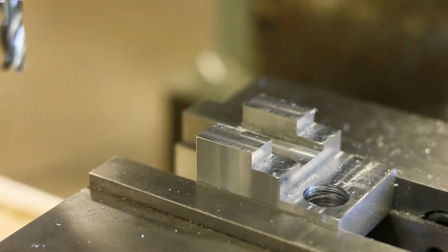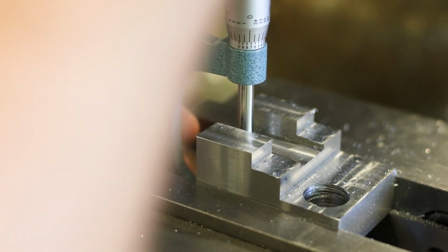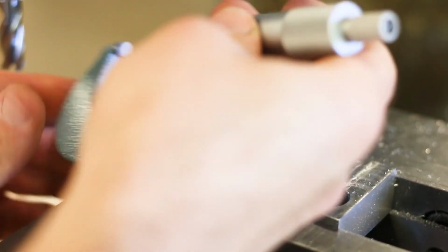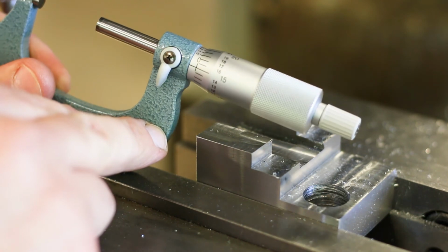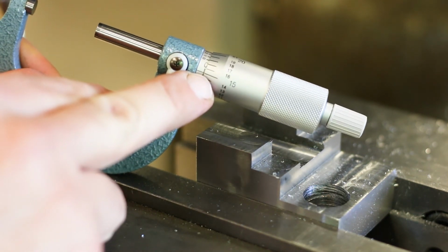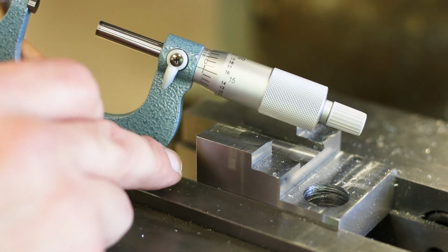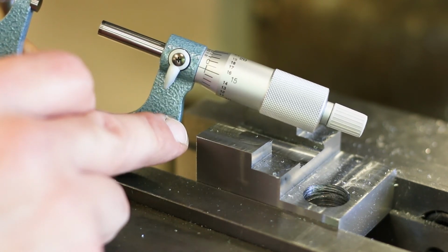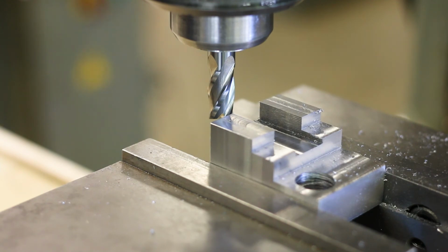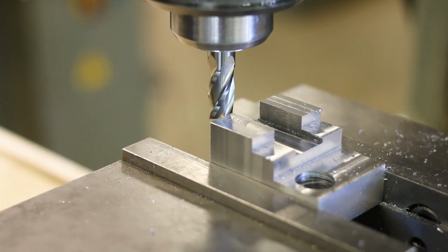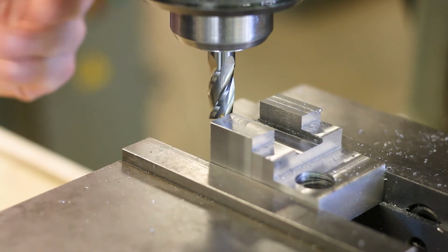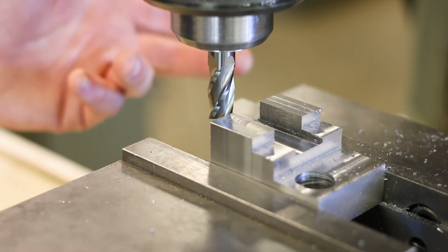Okay, there we go. Okay, let's go ahead and take a measurement right over top of where we just took our cut. Okay, lock it down, remove it, and that's telling me 1 inch and 15 thousandths. Remember, the final dimension is 1 inch, so we need to go another 15 thousandths. Okay, so I'm going to go ahead and lift the knee 5, 10, 15 thousandths right there, and then I'm just going to forget about it. The depth of the slot will just come in naturally as I'm taking my other cuts.